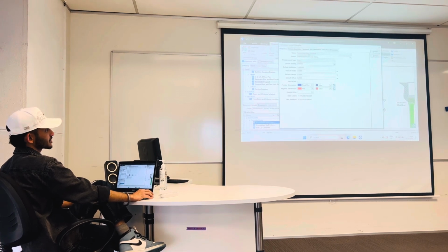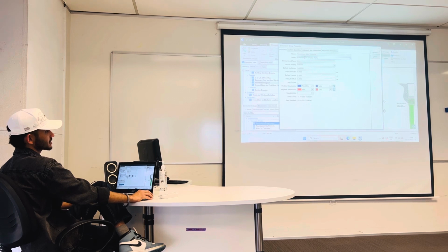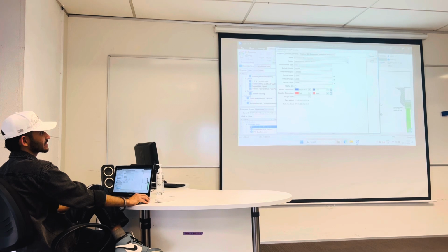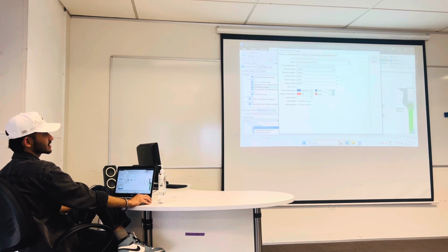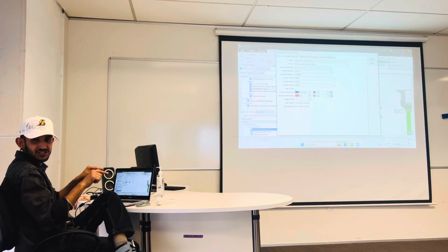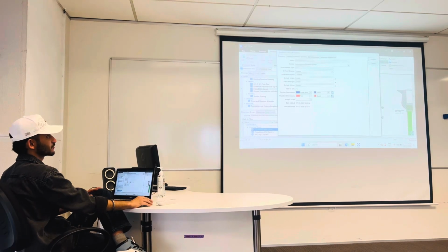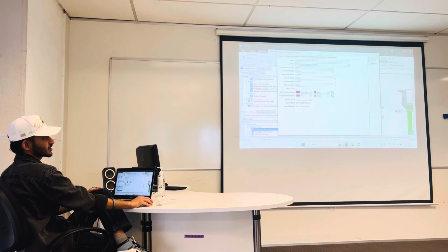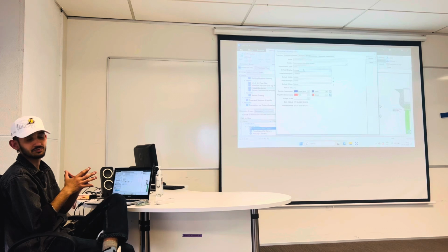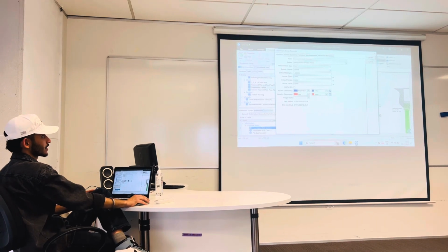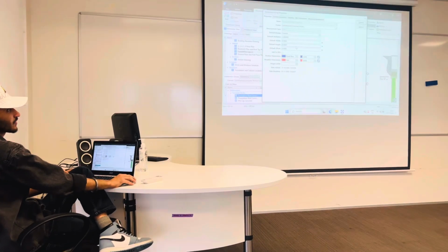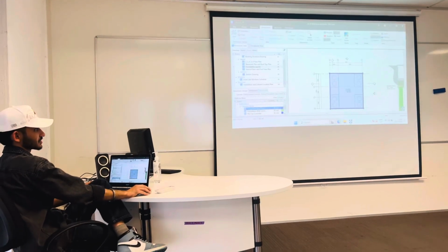So we put the name as foundation base concrete. The folder is substructure and the subfolder is concrete works. So we put the backslash in between. Then the measurement type is area, but the default display is volume, because we have the drawings. So we will measure the area, but the default display will be in volume because we are measuring the concrete. According to ANZ the concrete measurement unit is cubic meter, which is volume. And default multiplier, default height will be put 0.5 according to the drawing, and we'll do insert.